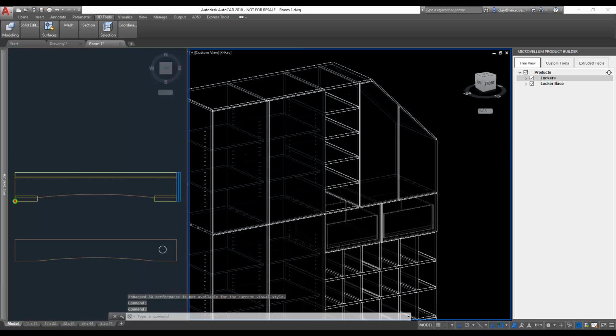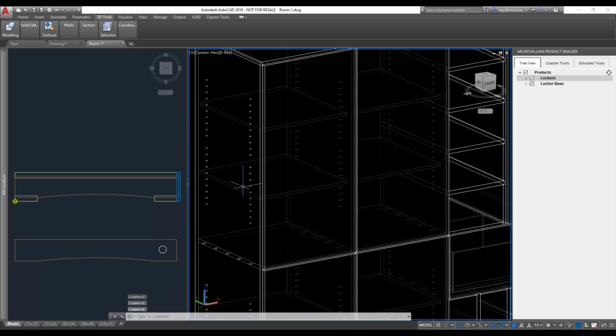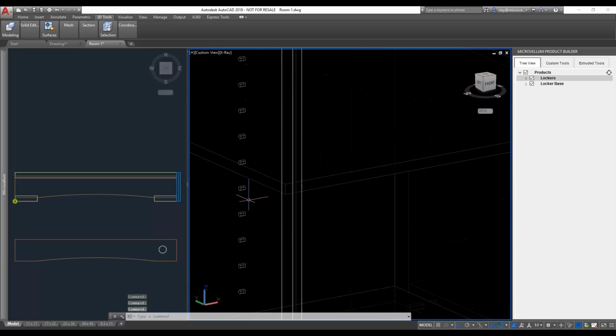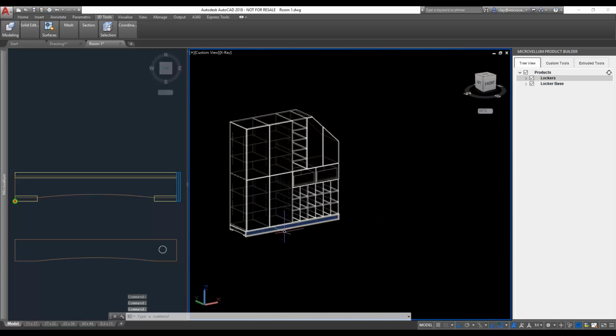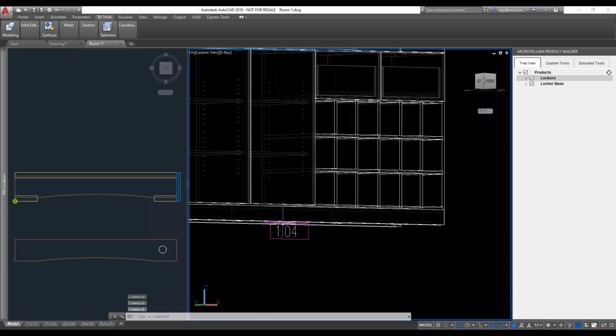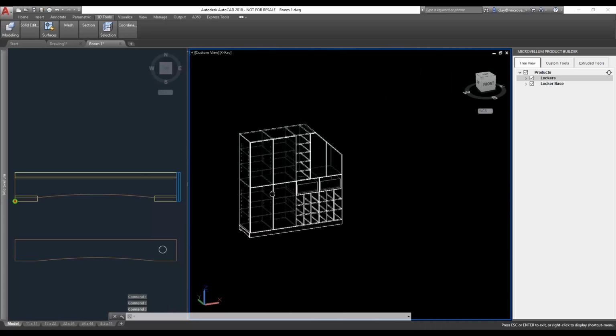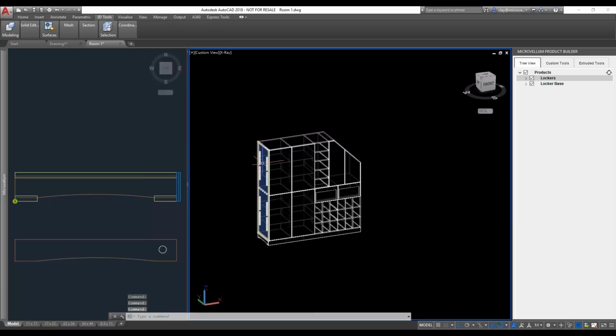So we can see that we've got all the angles, we have the miters, we have the machining for the dados. Everything matches up with a mirror copy of what we had created from just the solid model, but one thing's different. These are now Microvellum parts, and this is now a Microvellum product with machinable parts, and so you can see we have the item number down there below. So we can draw a part in 2D and see some of the machining for that, but let's skip that.